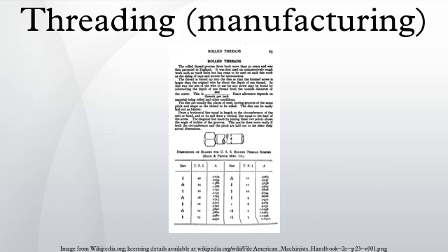Center-type grinding with an axial feed is the most common of the 3. It is similar to cutting a thread on a lathe with a single-point cutting tool, except the cutting tool is replaced with a grinding wheel. Usually a single ribbed wheel is used, although multiple ribbed wheels are also available. To complete the thread, multiple passes are commonly required.